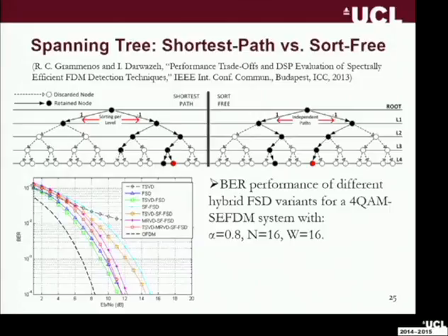So we thought, okay, instead of doing first all the real parts and then all the imaginary parts, what if we permuted between the two, so do real, imaginary, real, imaginary, real, imaginary, and we found that that did actually improve the results using the simplified sort-free version of the algorithm. So you can see here the ideal response is the green one, TSVD FSD, and the improved simplified algorithm by using the modified real value decomposition, the blue one, is quite close.